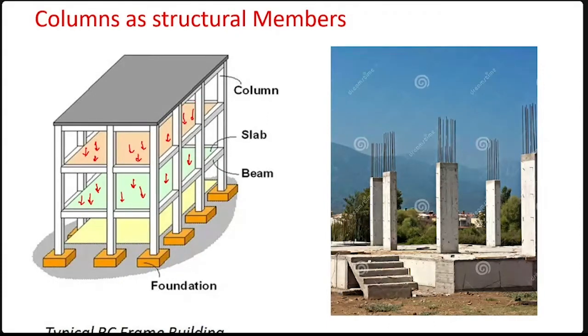Floor load, as you understand it, is composed of dead load, live load, and so on. Wind load and earthquake load usually do not apply on the floors. So floor load is basically dead load and live load. So you understand that every floor will have identical loads.